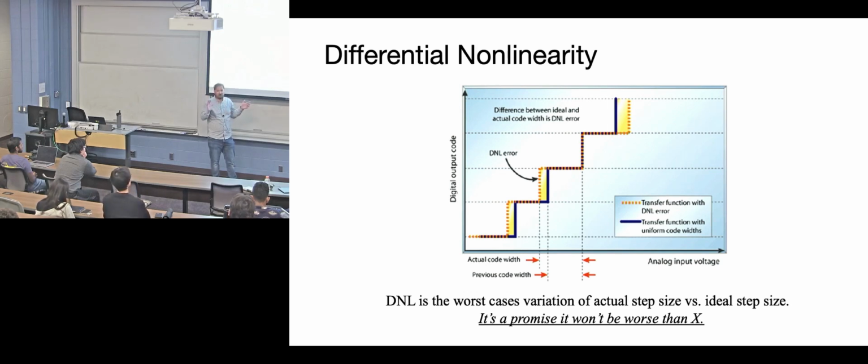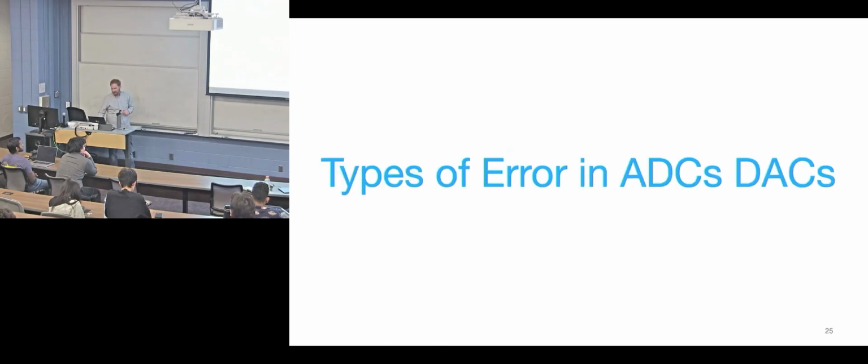And certainly couldn't do it in a production environment. That just wouldn't work out. So linearity is the amount of variation you get, and then the manufacturers of your ADCs are going to give you some metrics on what they guarantee their linearity to be based on their fabrication techniques in the device itself. What other questions do you have on trade-offs?